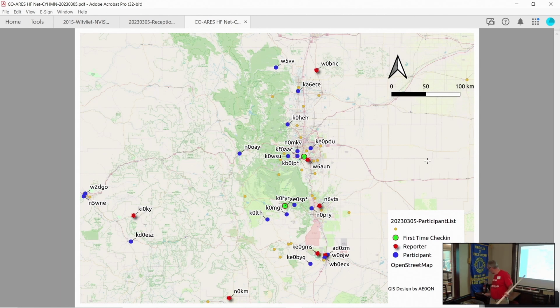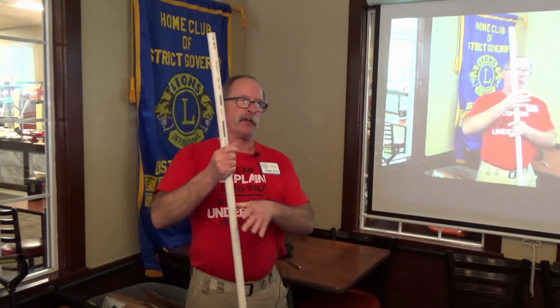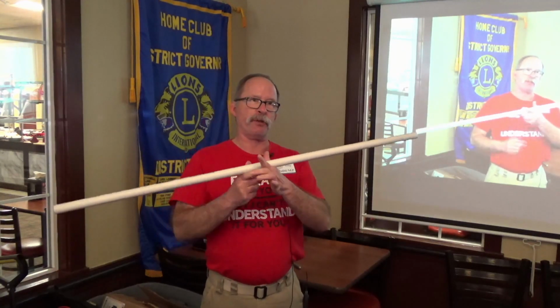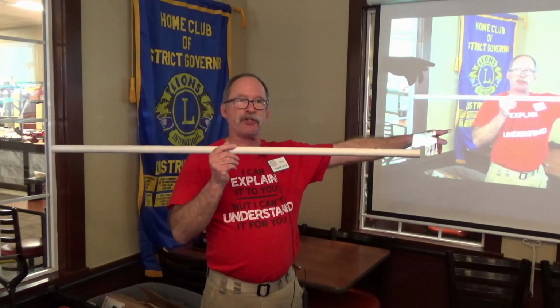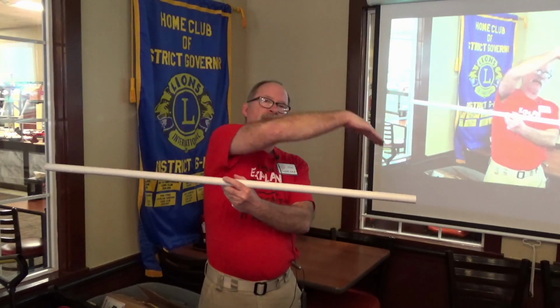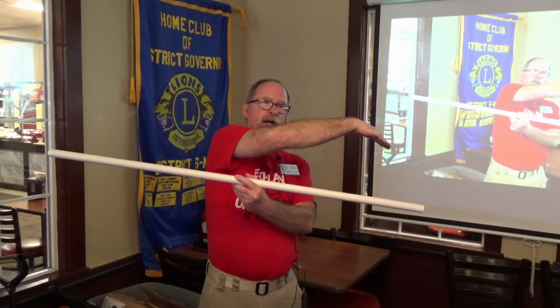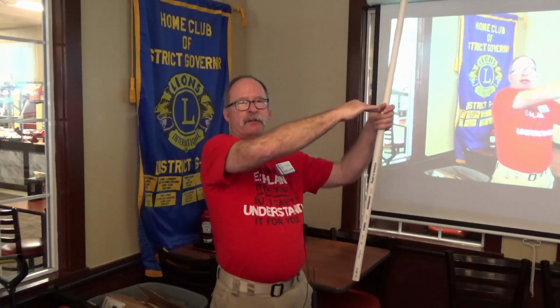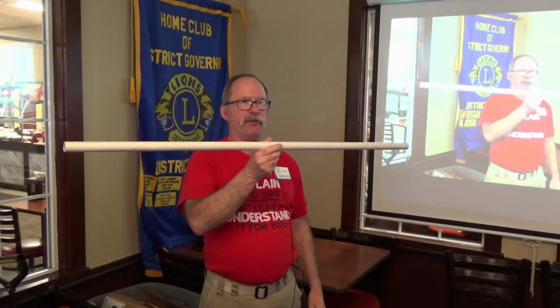That reminds me of a question that comes up. If you're going to work NVIS, you want the person on the other end to have an NVIS antenna as well, especially the closer in you get. If I've got my NVIS antenna in Poudre Canyon and I'm talking to the guy in Grand Junction, it probably doesn't matter because at that further distance, I'm coming down to him or her at an angle, right? So if they had a vertical, it would probably be okay at 200 miles out. But if we're all working together in Larimer County or Larimer and Weld County, everybody needs a horizontal NVIS antenna.